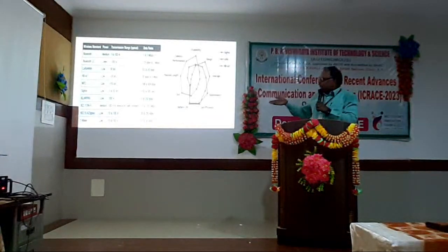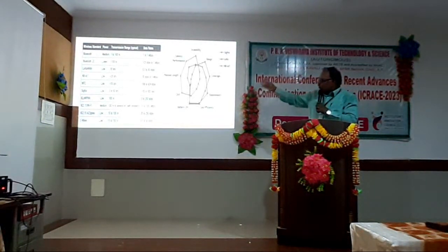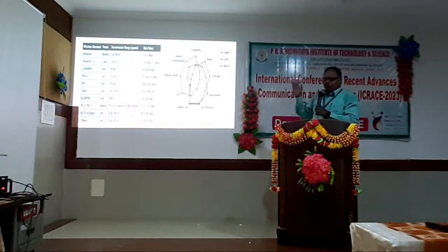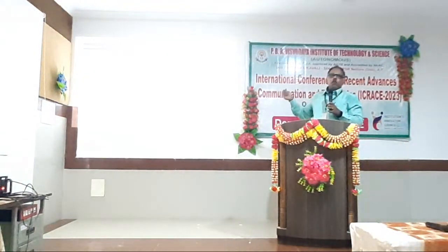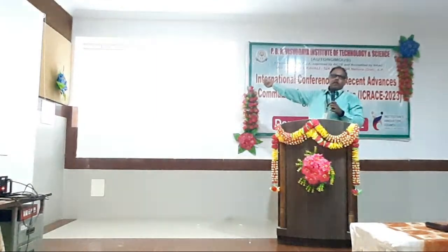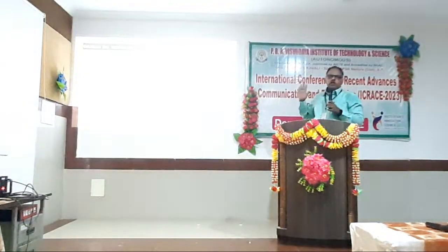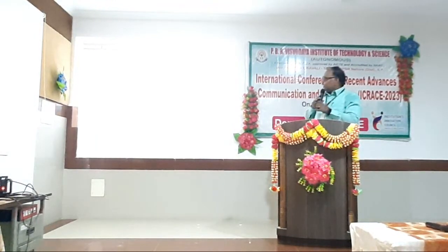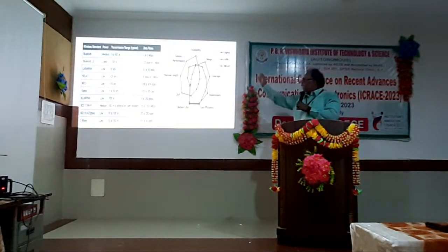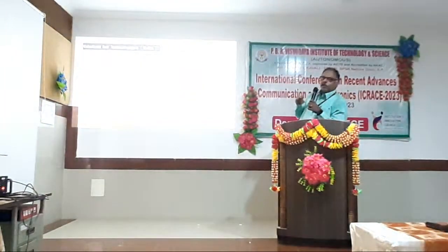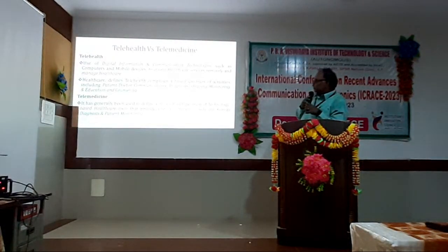In terms of Sigfox, we can see that 100 to 600 bits per second is going to cover about 3 to 50 kilometers. So based upon the situation, I can decide what type of low power communication technology to look at. That's the basic thing, where more focus is on the selection of the technology, like scalability, range, and how Sigfox performs for range and coverage. This chart projection shows which acts best. Next please.